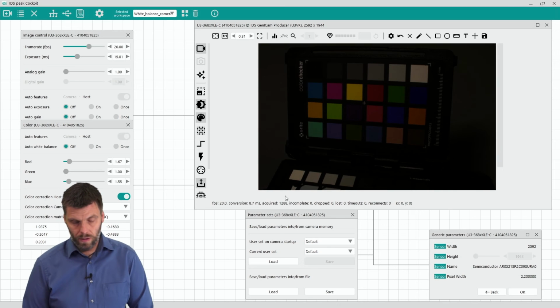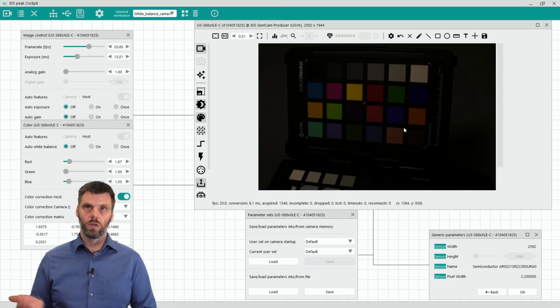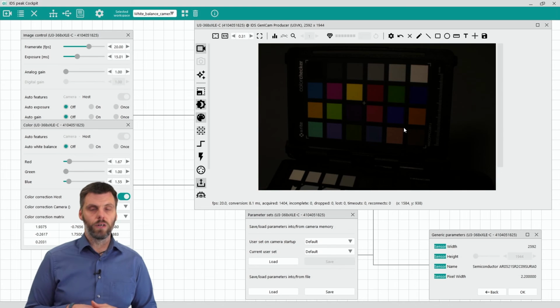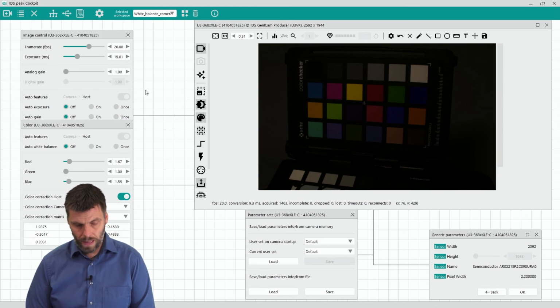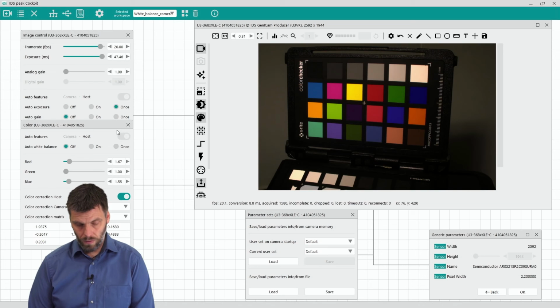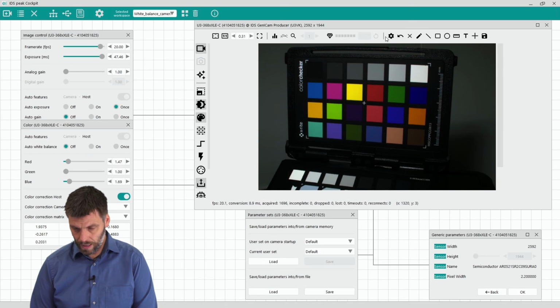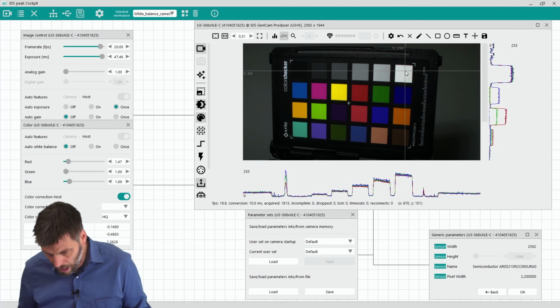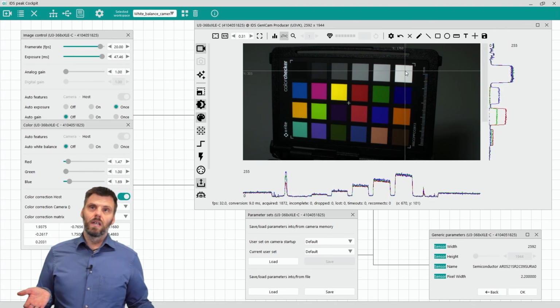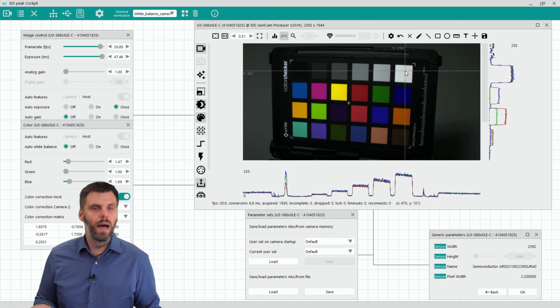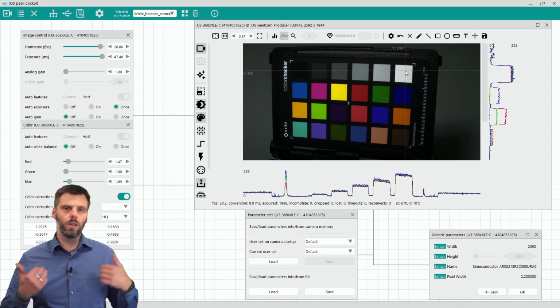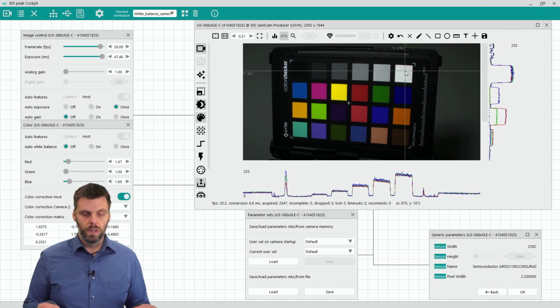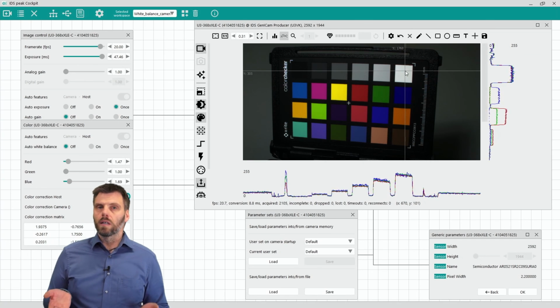Okay, and also here, I wouldn't let you go without showing a nice image from an IDS camera. We use now again the auto features. We set auto exposure to once, quite nice. We set auto white balance to once. And then we can check with the line view if it fits our needs. And I would say this is nearly as good, or it is as good, as we did it manually. So also here, don't be afraid to use the auto features of IDS Peak.